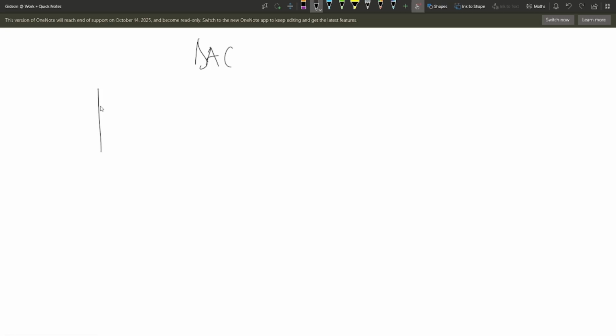So its circuit symbol looks something like this. We have plus and minus over here, and then we have the power terminals, normally VCC and, let's say, VDD. Now we have V minus and V plus. V minus is also called the inverting input, and V plus is called the non-inverting input. Later on, as we go on, you will understand the reason why we call them that.